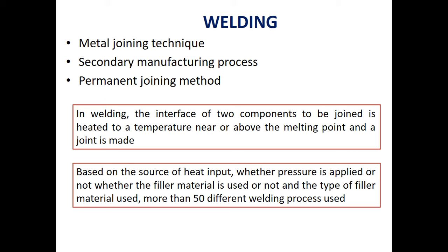Maybe mechanical fastening using nuts, bolts and rivets. And another joining technique, adhesive bonding using glues and resins, isn't it? Yes, welding, of course, soldering, brazing. You may have done some kind of soldering. All these are metal joining techniques. Now, the joining techniques which I have explained, the fastening as well as the bonding, are temporary or semi-permanent joining techniques. But welding is a permanent joining technique.